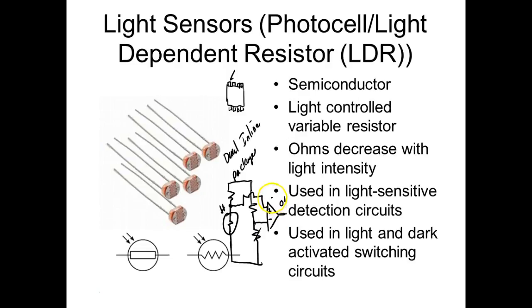Sometimes they power them on a plus and minus supply, and if the inverting input is greater, it'll saturate negative. If the non-inverting input is greater, it'll saturate positive. If they reference it to common, then this guy is not called the minus input, it's called the inverting input.